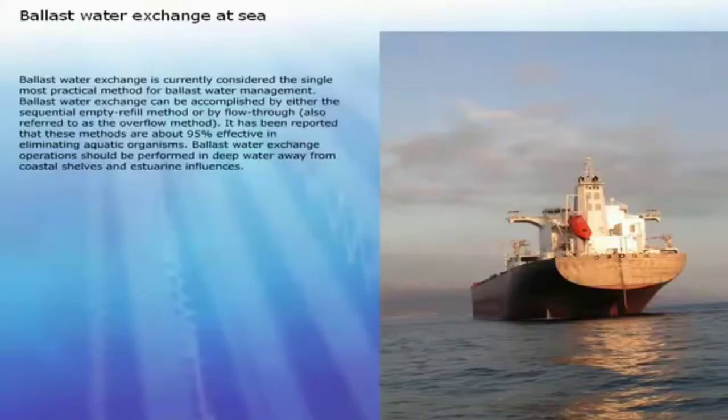Ballast water exchange can be accomplished by either the sequential empty refill method or by flow-through, also referred to as the overflow method. It has been reported that these methods are about 95% effective in eliminating aquatic organisms. Ballast water exchange operations should be performed in deep water, away from coastal shelves and estuarine influences.